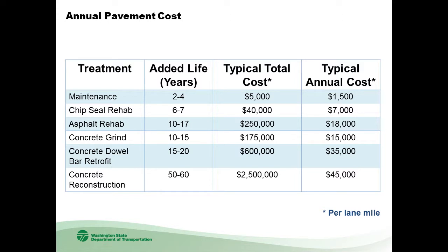Do we include engineering costs? Do we include traffic control costs? In Washington, we include sales tax. Oregon doesn't even have a sales tax. So if we want to start using these as performance measures to compare state to state how cost effectively we're managing our pavements, we really need standards to define what goes into these cost effectiveness calculations.